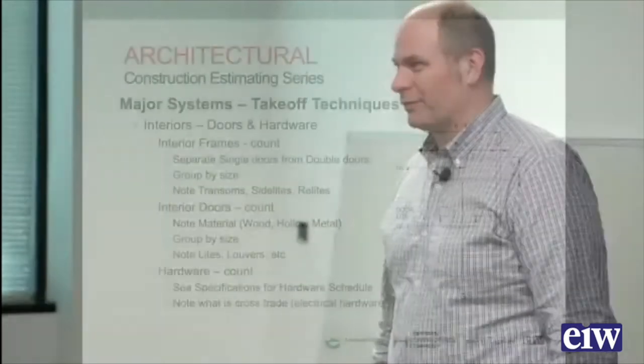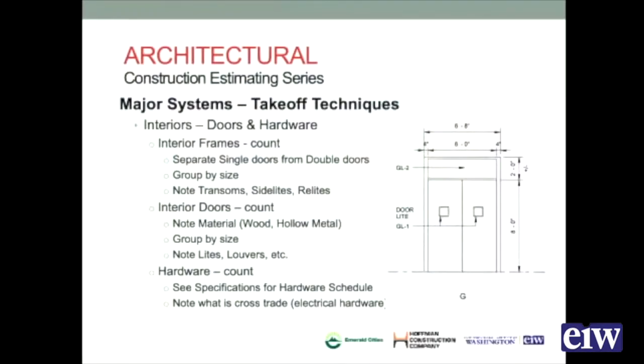So you need to understand those things because you've got to have access to get the material in. And grout, cementitious grout, isn't something you're really going to put in beforehand and then install, because it's going to make the door frame really heavy, and it's a fluid system, so it would be very hard to actually do that.